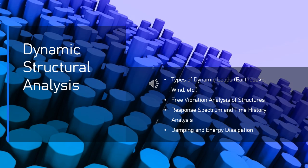Step 3. Modal superposition. After the response spectrum is obtained, the individual responses for each mode of the structure are calculated. These responses are typically linearly superimposed to determine the total response of the structure. This approach assumes that the modes do not significantly interact with each other, a simplifying assumption that holds true for most practical cases. Key features of response spectrum analysis.